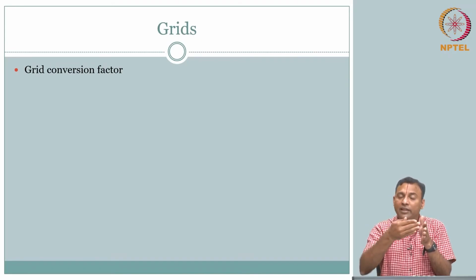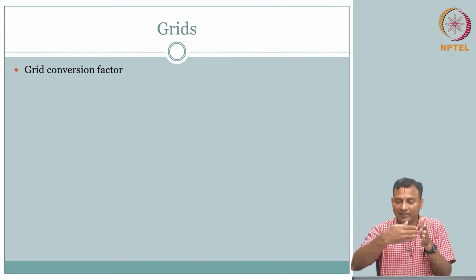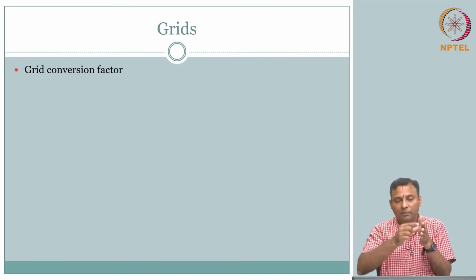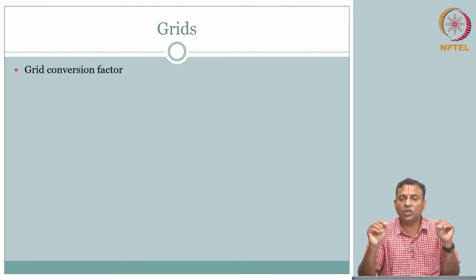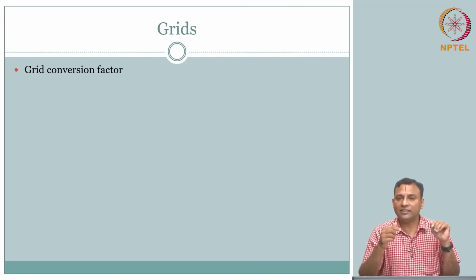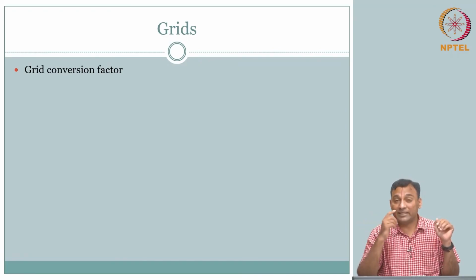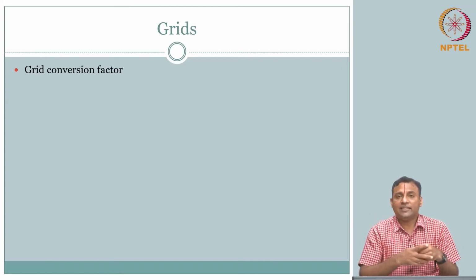The height of the lead controls which angle is absorbed, but whatever is coming and hitting the lead itself is also lost. Your signal is also lost wherever the leads are physically placed. So, in some sense I have reduced my noise, but I have also reduced my signal.